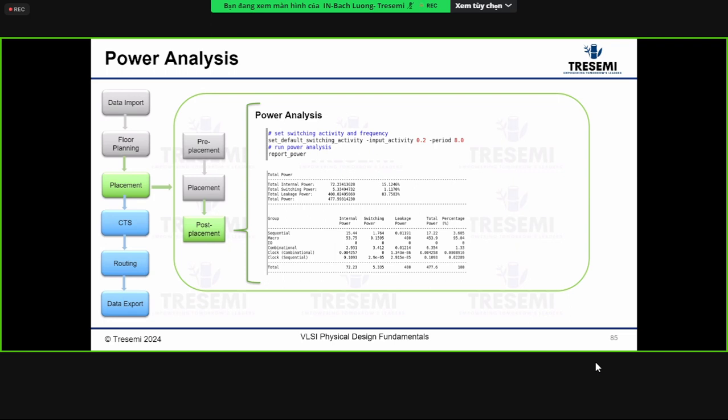Okay, so no one. All right, the reason is, remember, the clock tree is a big portion of the switching, right? So in placement, we don't have the clock tree yet. There's no clock tree. That's the reason why the switching is currently low. So when we build the clock tree, expect these numbers to grow to be a lot bigger. Okay, so here the leakage dominates.